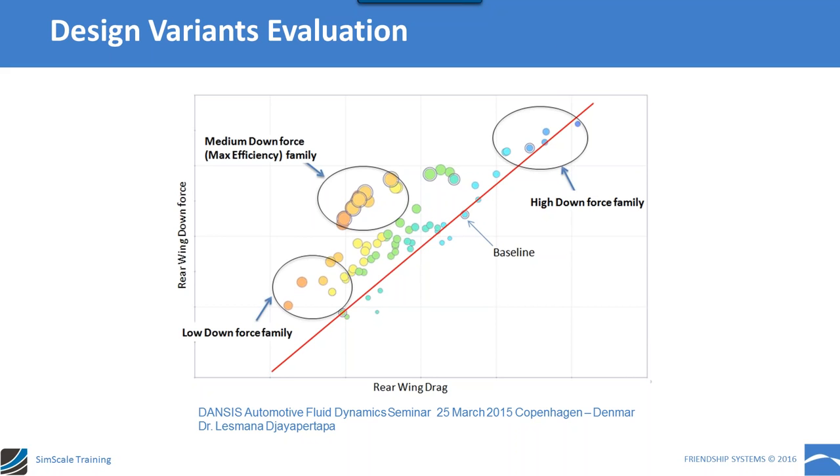And like we have talked about in the first presentation, in the F1 session, we have different circuits. So circuits where you need high downforce, circuits where you need low downforce, so you need more speed, and almost all the circuits are approximately medium circuits. So we will have already from one optimization run different candidates for high downforce or low downforce or even for medium downforce.